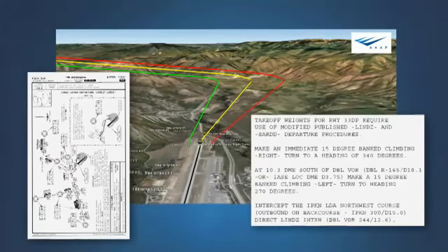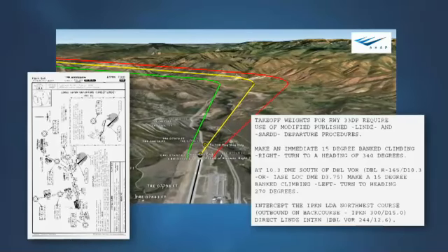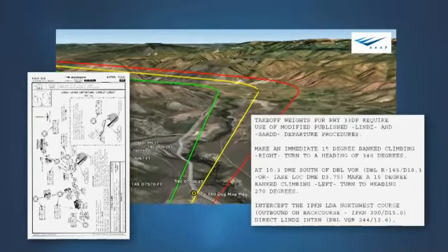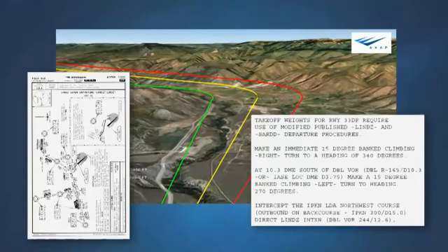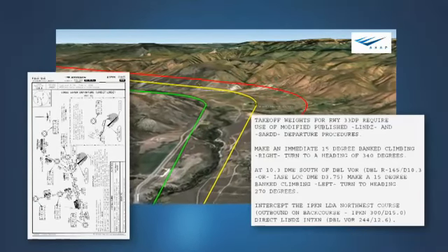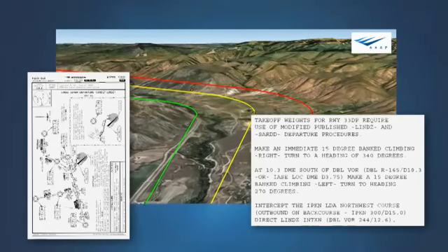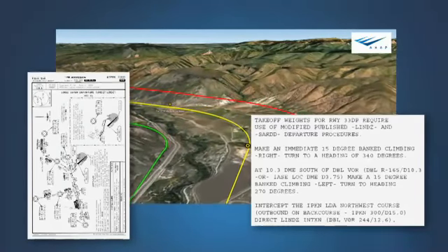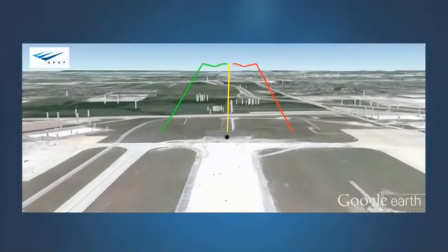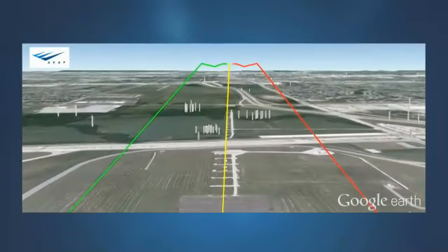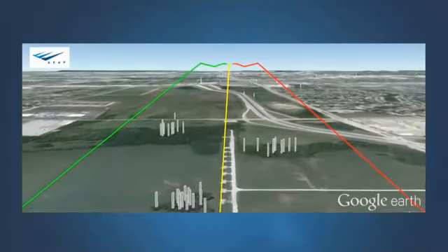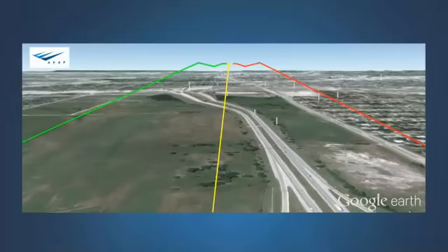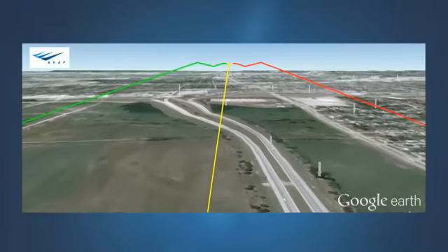If it is not already available, it may be appropriate for the operator to request an engine failure procedure that does align to the SID or ODP to the extent necessary for the airplane to reach the IFR en route environment. As we saw at Aspen, this may involve the use of a conveniently located holding pattern. However, some additional pre-departure planning may be required when the engine failure procedure maintains a straight-out track, or if the engine failure procedure differs significantly from the IFR departure procedure.